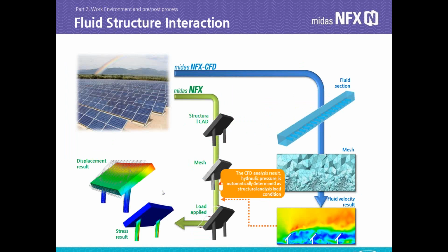And NFX has some kind of fluid structure interaction as well. So what you can do is do the CFD analysis, and when you get the final fluid velocity and pressure result, you can export the pressure result on the structural model. So you can create separately your structural model and export it as a load, and then check the structural results. I'll show you that right after during the demonstration, how you can do that.